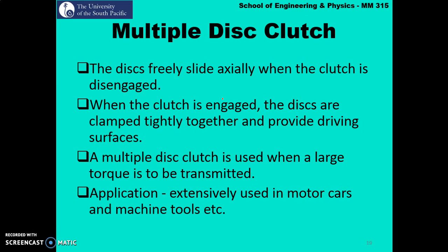One of the problems is that, for instance, you are required for a machinery that in the beginning was able to cater for a torque transmission of, let's say, 100 Newton meter. Now for that same machine, the requirements have increased and you are required to transmit 150 Newton meter. So you've got several options. You will change the clutch system entirely. Previously you had a smaller clutch system, so to transmit larger torque you might need to use a larger clutch system setup. So that's one.